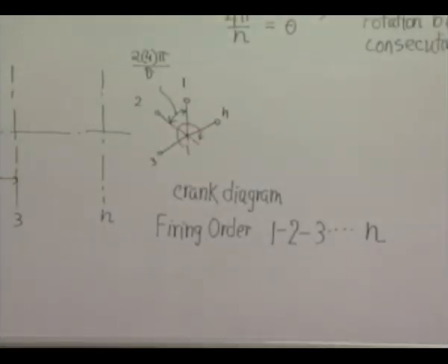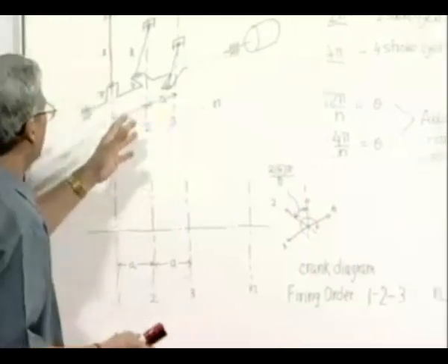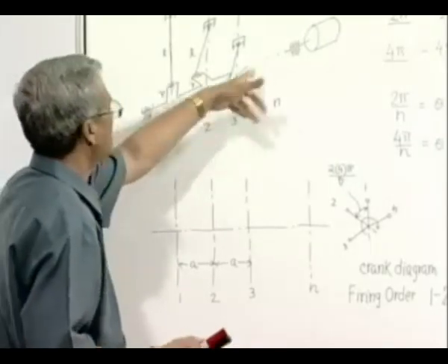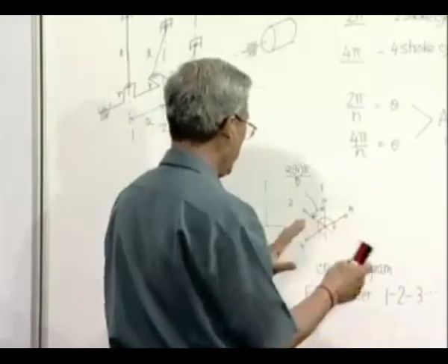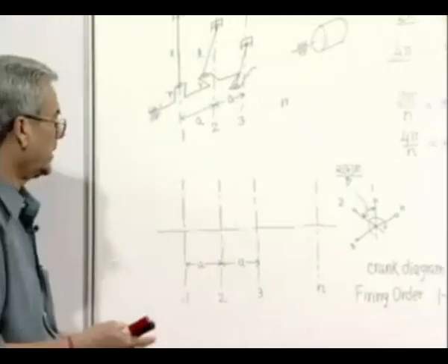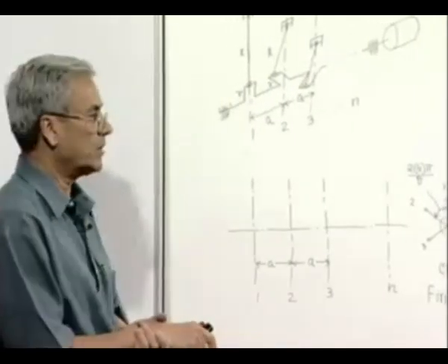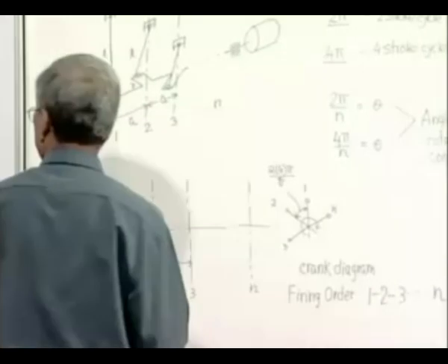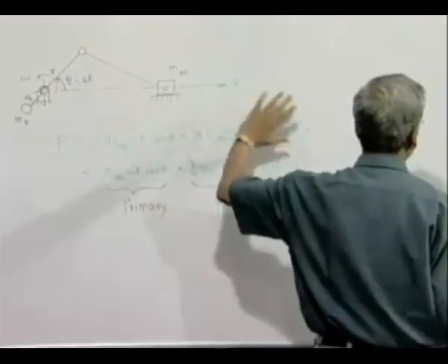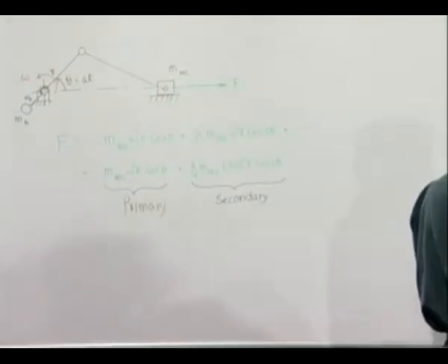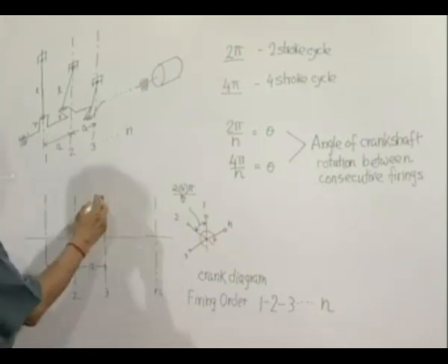Now you will see, as we will find out, that this firing order is very important, because according to that only the crank locations will be arranged. And the same engine with a different firing order and different crank settings can behave differently from the point of view of balancing of its forces and moments. Now, in case of a single slider crank system or single cylinder system, there was only a matter of force. But now we will also have a moment, because force is acting at different lines, and therefore,